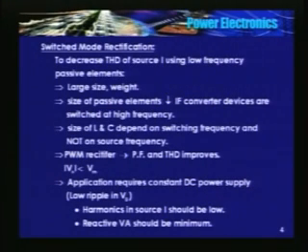So in a PWM converter, I told you that there are a large number of pulses, and the frequency of the predominant harmonic increases, but the magnitude of the output voltage is proportional to the modulation index. The modulation index can take a value of 1, so the output voltage is always less than or equal to the supply voltage. The power factor of the PWM converter is approximately equal to 1.